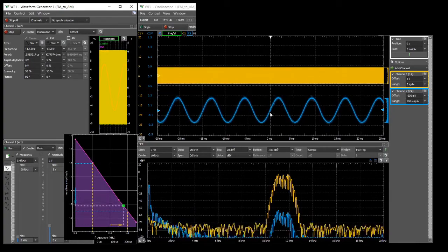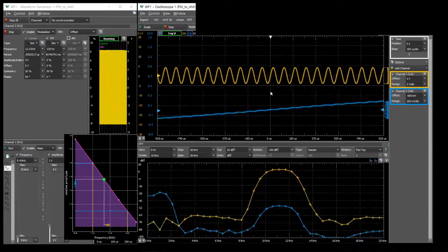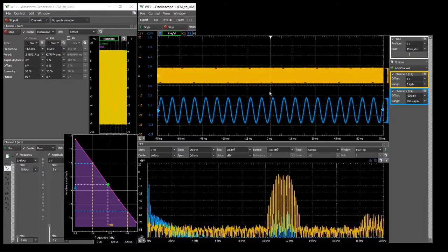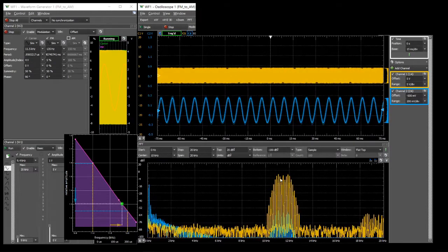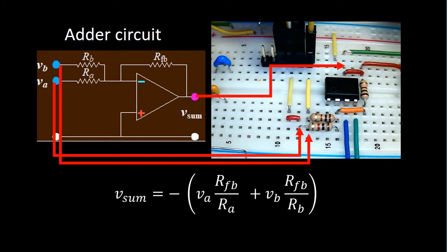Sine wave is the most economical modulation for the bandwidth, and it can be used to study the frequency response of this FM system. The previous technique of demodulation is of the passive type. It has the advantage of simplicity, but also some disadvantages. A more common technique is active demodulation using heterodyne, or nonlinear mixing, also known as coherent detection.